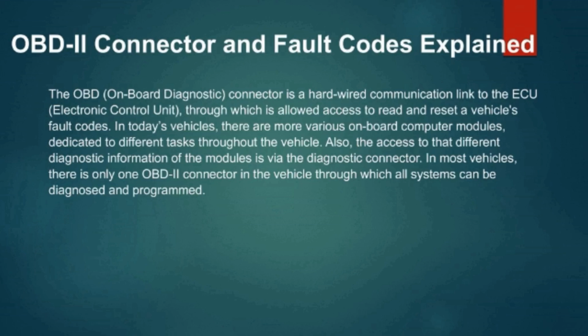In today's vehicles, there are various onboard computer modules dedicated to different tasks throughout the vehicle. Also, the access to the different diagnostic information of the modules is via the diagnostic connector. In most vehicles, there is only one OBD2 connector through which all systems can be diagnosed and programmed.